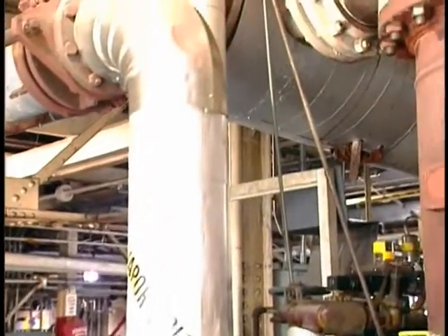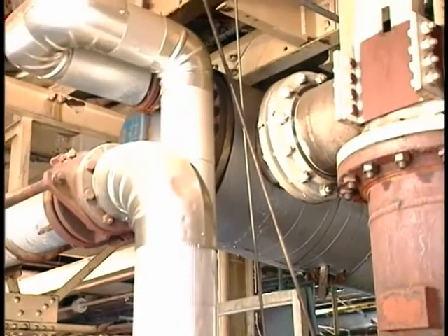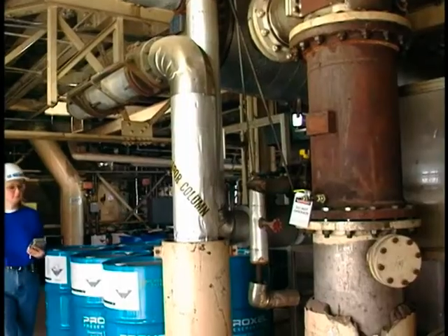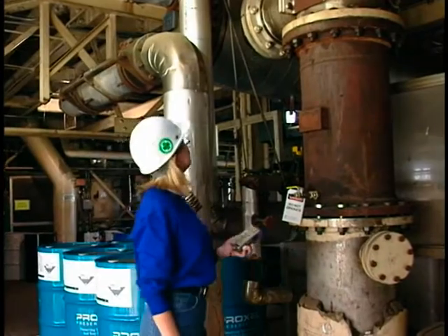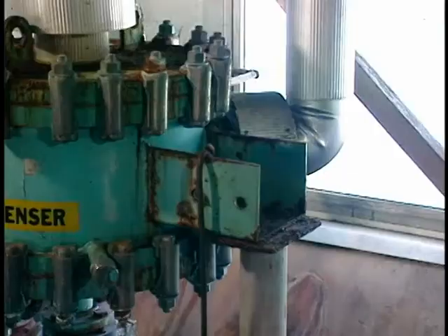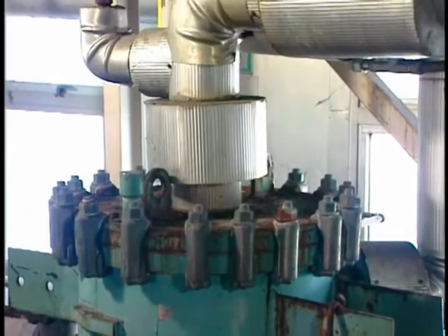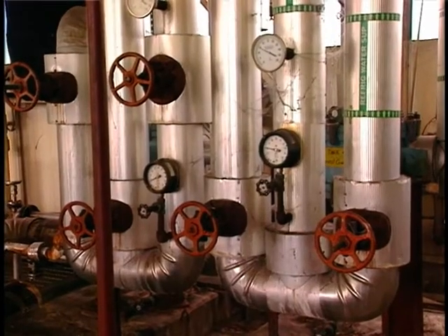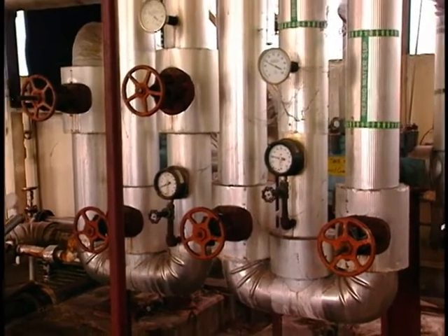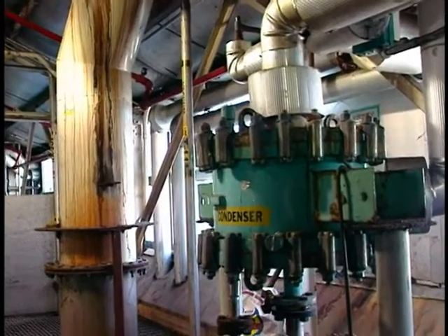Decreased gas flow rates will result in reduced capture of the contaminants at the source, resulting in fugitive emissions. Low gas flow rates may result from the buildup of ice or frozen organic compounds in the condenser. Decreased fan motor currents and decreased hood static pressure indicate a decrease in the gas flow rate.